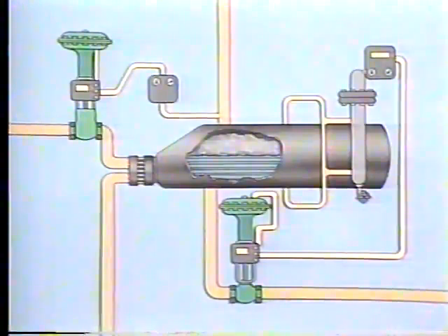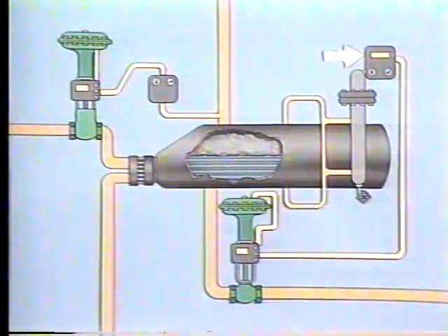Now that we've seen how the steam flow's control system is set up, let's take a look at the control system that's designed to maintain the level of water in the shell. As we said, the water level must also be controlled to maintain steam pressure out of the heat exchanger. In this system, the water level is sensed by a displacer that's connected to the level controller. Like the pressure controller we saw, this level controller also combines the measuring and controlling functions in one instrument.